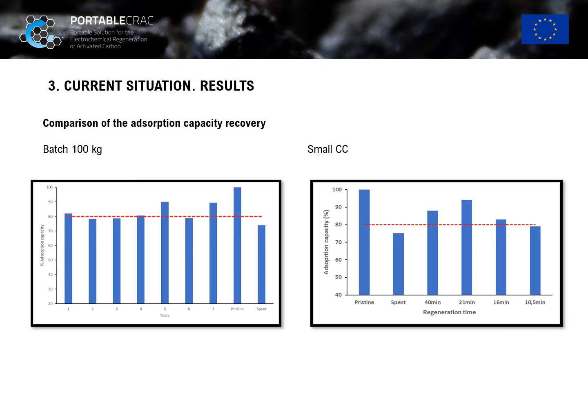Regarding the regeneration performance assessed from the tests carried out with both the batch and the small CC prototypes, the results were favorable. Four of the 7 tests carried out with the batch have shown that the adsorption capacity can be recovered above the 80% mark in 1 hour, which is the threshold set by the project. Likewise, the results obtained with the small CC show that it is capable of achieving a recovery of the adsorption capacity above the 90% mark in just 21 minutes.